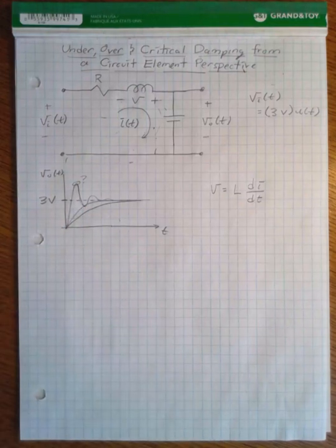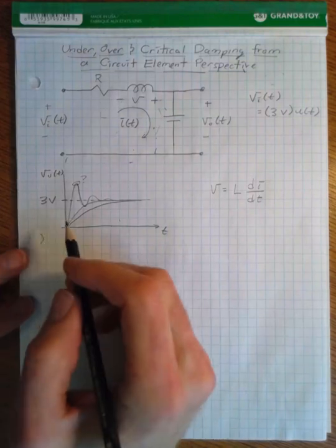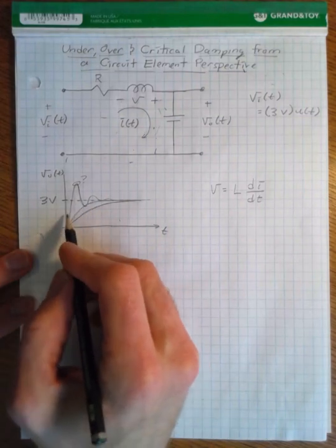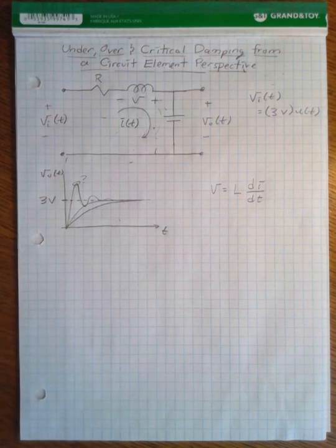And typically when you're designing a control system, you don't want to have oscillations, right? Like imagine you're designing the cruise control for a car. You don't want to be overshooting your desired speed and undershooting constantly. You want to just converge to that speed. And so in that case, you would typically try for a critically damped system, something that responds as quickly as possible, but doesn't go through any unstable oscillations.